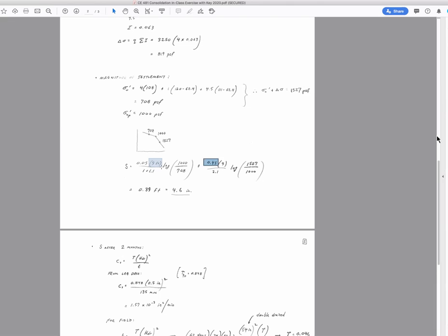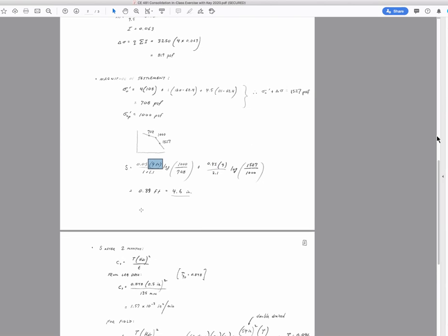An important aspect here is that it's the entire clay layer thickness. We'll get to the drainage, and if you take that in half for a double drained and so on, that comes in only to time rate stuff. But settlement itself is a strain-based calculation, and it's the entire clay layer, 9 feet thick, which is straining indeed. So we need to have that be the full amount.